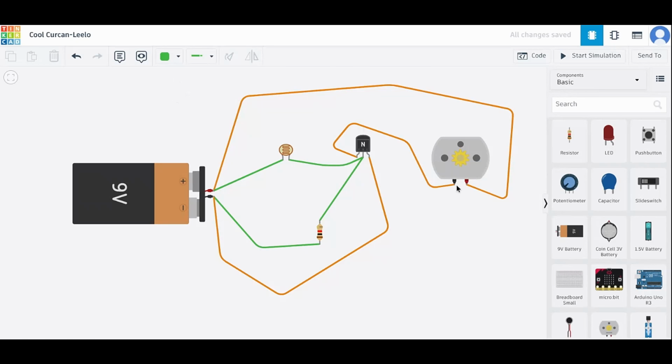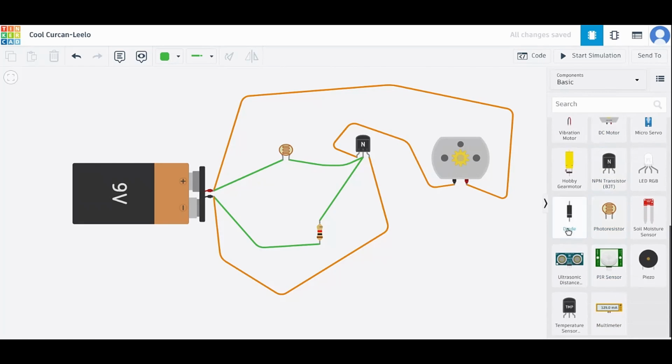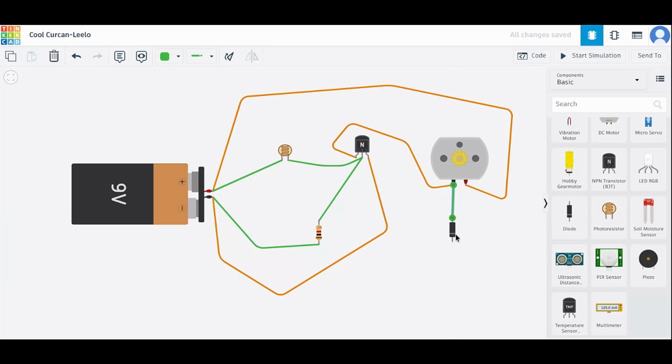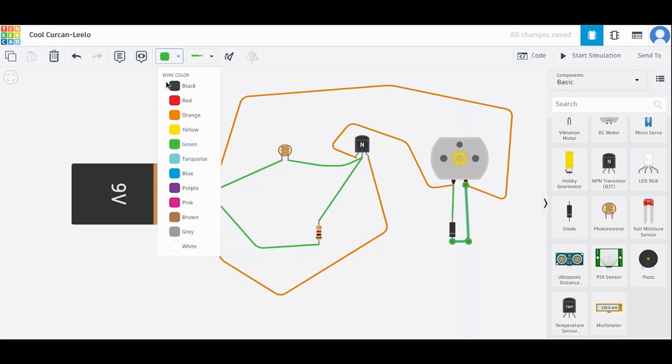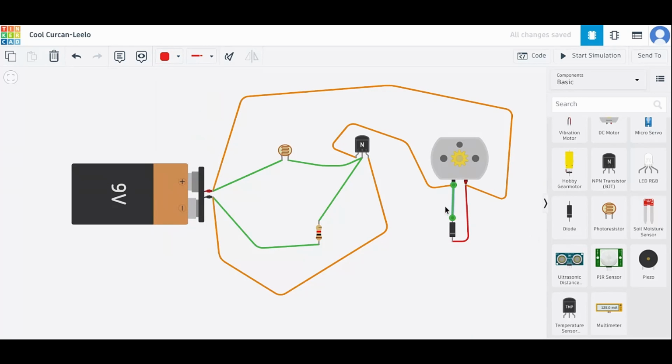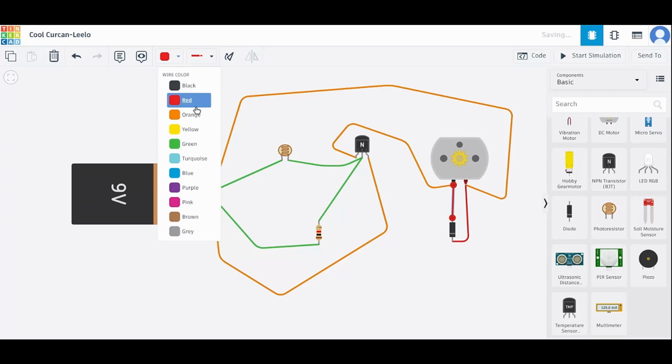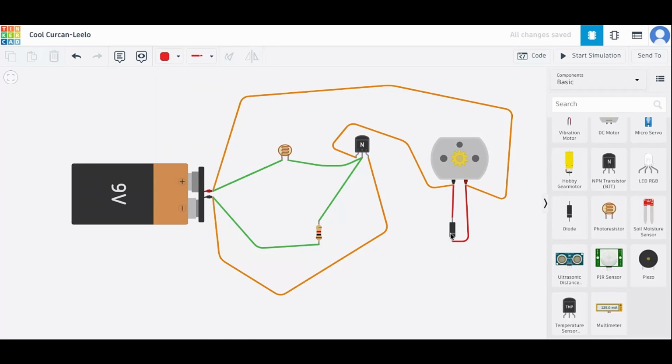The way that you do it is by having control over the direction of current flow here. So I'm putting a diode. Okay. So here, based on the symbol, current can flow from top to bottom. Think of it as a circuit protector. So let's take the red one. Something to name for that is a flywheel diode. It has a couple of other names.